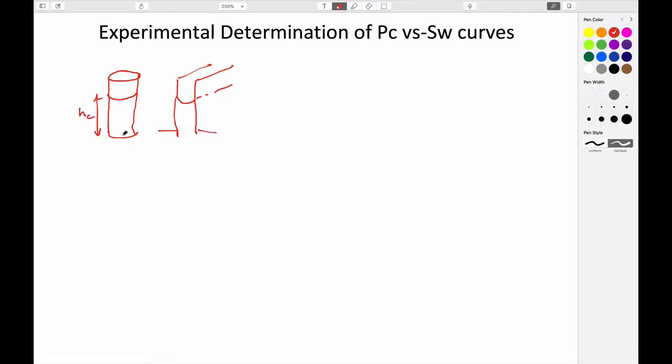below a level of fluid. And we identified a couple expressions. One was that the height rise, critical height, was something like 4 times interfacial tension divided by the unit weight of the fluid and the diameter of this tube.